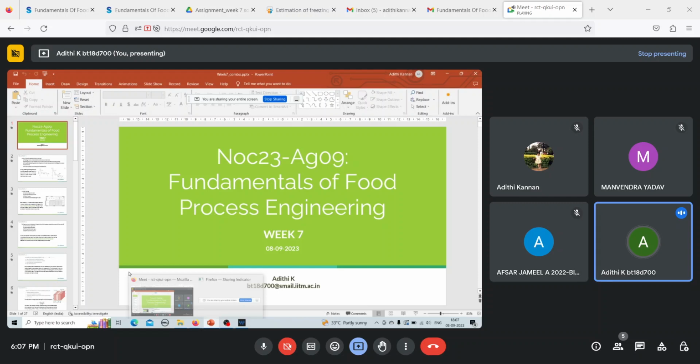the ice will start forming from the surface to the center. That movement of ice from the surface to the center is known as the movement of the ice front. So freezers can be grouped according to the rate at which ice formation happens. Examples of slow freezers are still air freezers or cold stores. That is, you just have a large room with cold air circulating naturally inside it, and that cold air will freeze your product.